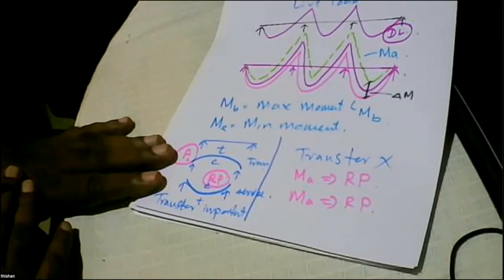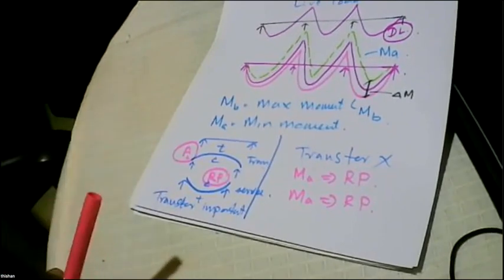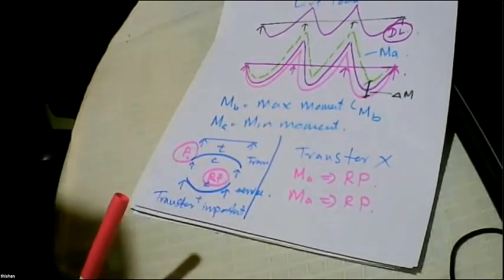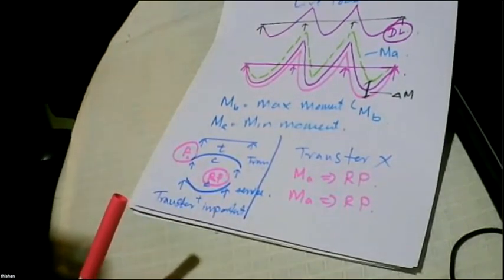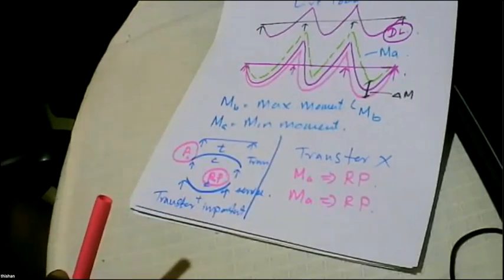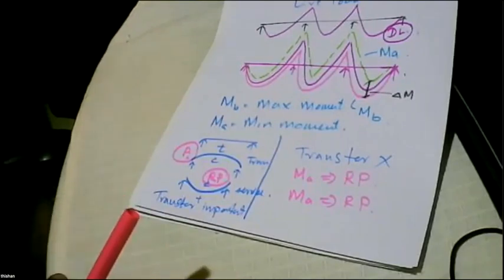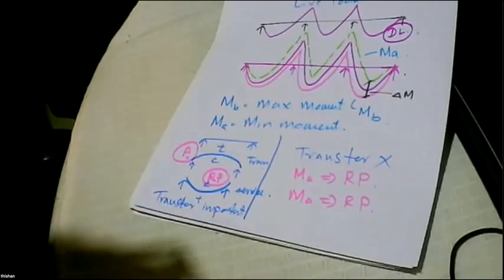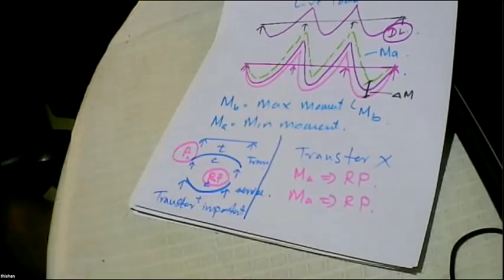Because we have a very favorable huge top flange. That's one side. On the other side, we have a very strong steel at the bottom because the steel breaks only at 1860, whereas the steel is stressed only about 920. So we can double it. That means there's a huge capacity in the pre-stressing wires, so that with a minimum amount of pre-stressing wires, you can satisfy the ultimate moment carrying capacity in composite construction.